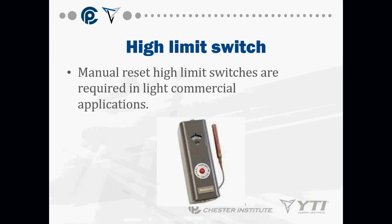You may have high limit switches on them. Some do, some don't. They can either be manual reset or automatic reset. Your high limit switch is going to either test the temperature of the water in the boiler if it gets too high, or it's going to shut off the boiler based off of the burner temperature, depending on the type of application we're dealing with.